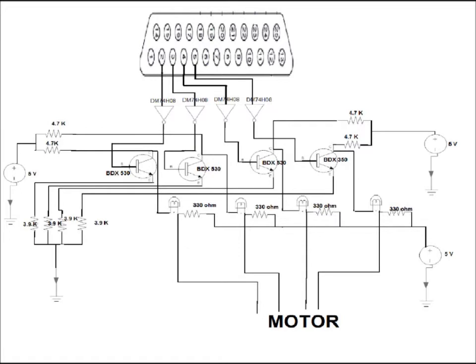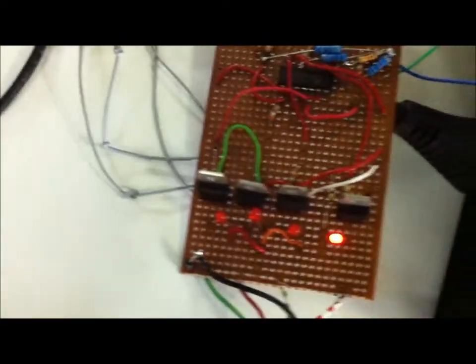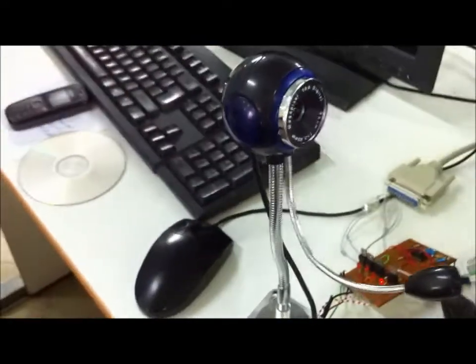We used the parallel port to send the signals from the computer to the controlling circuit, which is shown in the figure. As we can see, we used 4 data pins to send signals to each coil, activating them one by one. The circuit consists of 4 BJT transistors that work as switches. To activate a coil, we send 0 volts to the BJT and 1 volt to deactivate the others. Repeating this step 4 times will cause the motor to rotate 1 degree.